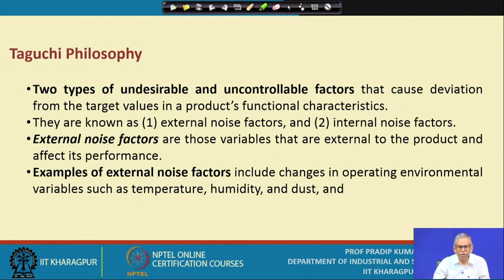In each quality characteristic, you have to identify the best possible nominal value or the desired value. Is it okay? And you target to achieve this desired value. So it's not the mean value. It's basically the target value you want to achieve. And when you start using the Taguchi method for quality engineering, the target values must be known.